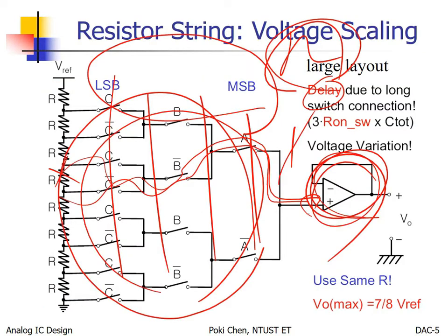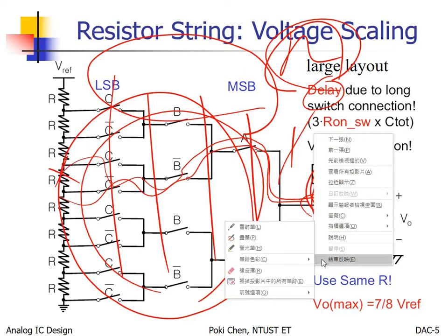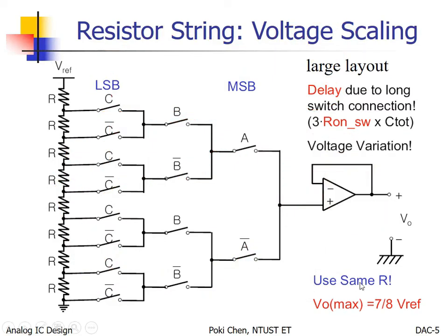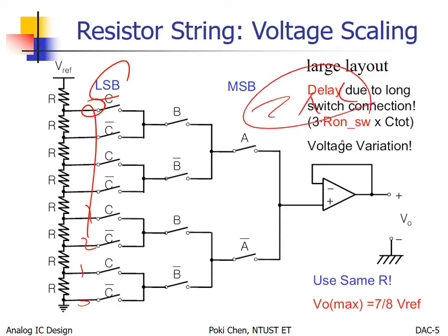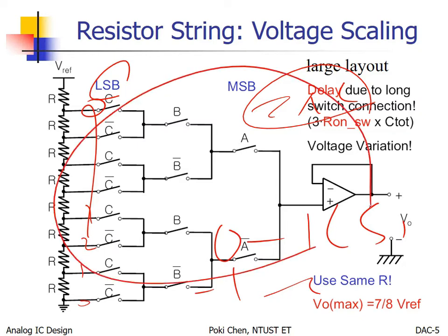Before that, the other issue is the breakpoints for the DAC. You can see 0, 1, 2, 3 all the way according to LSB, right? And according to the definition of our INL, this one is no good because the error will become between 0 to 1 LSB, or -1 to 0, as you like. Anyway, the maximum error for such a DAC is 1 LSB.